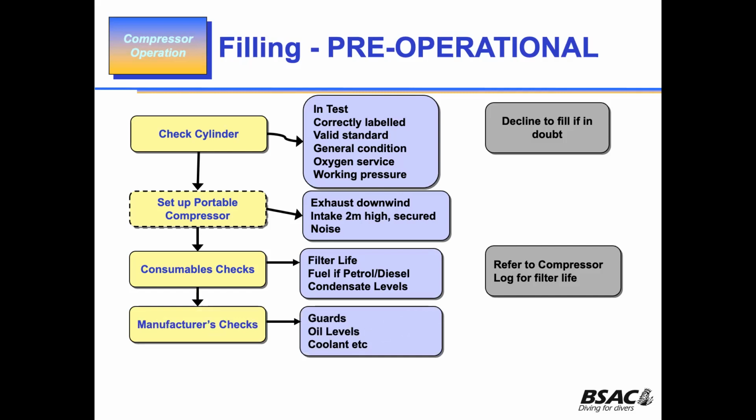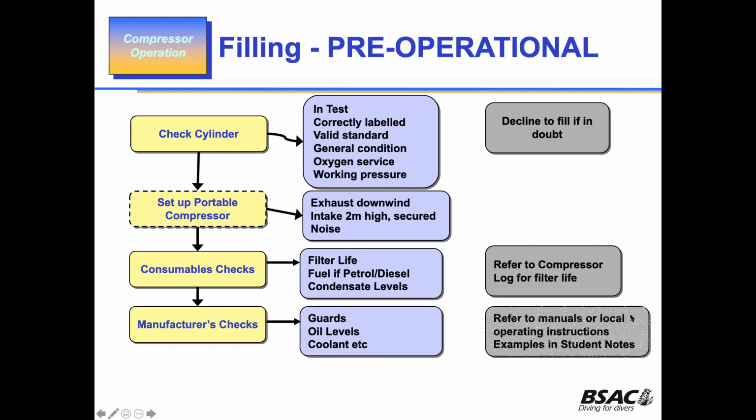Manufacturer's checks, that's guards, oil level, coolant, etc. It all depends on the type of compressor you're using. Refer to the manual or local operating instructions.